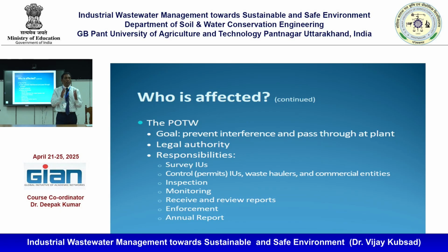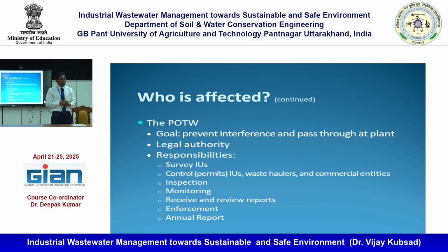So monthly you have to send a daily monitoring report. You will see how much wastewater is produced, how many parameters are measured, and whether they are exceeding what you have been given. If you are allowed 300 milligrams of TSS and they are producing 400, then you will see what happened. That is a numerical violation. You have to give an explanation of what happened and how you will reduce it.